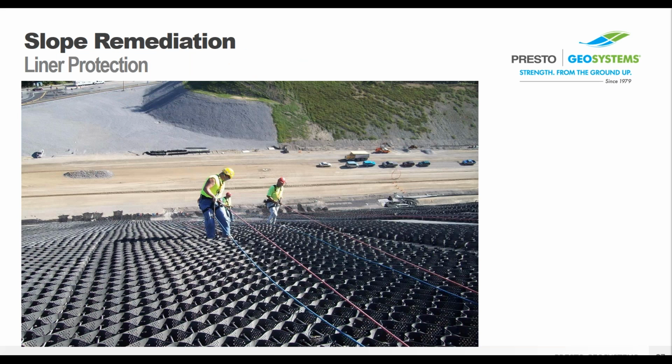And then a different thing that I want to highlight, I mentioned it a little bit before, was geomembrane liner protection. So if you are over a landfill, or doing some sort of collection or detention pond, that sort of thing, you're going to have a liner that you don't want to puncture.